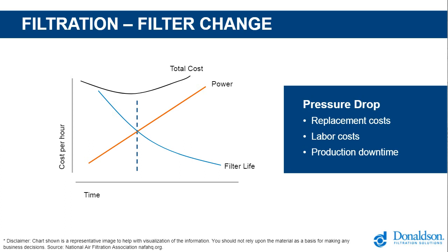We're looking at the hours of operation, emission levels, pressure drop, and how things are performing. We check that all the performance criteria are in the right place, to the point where, as in the graph Bart showed earlier, at that predetermined point something needs to be replaced, i.e. the filters. So condition-based is checking the performance of the collector and knowing when it's due for a service, rather than purely on a time-based system.